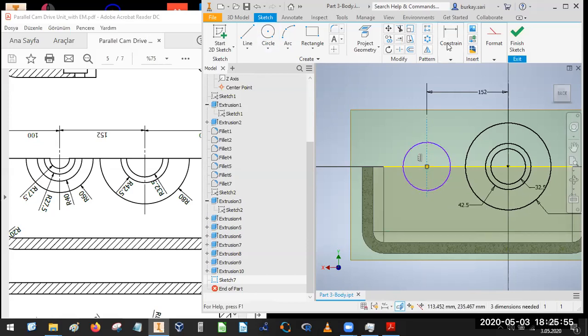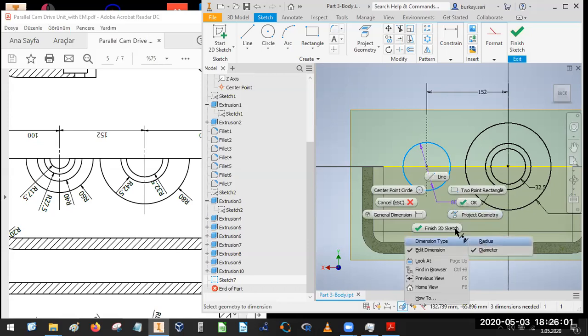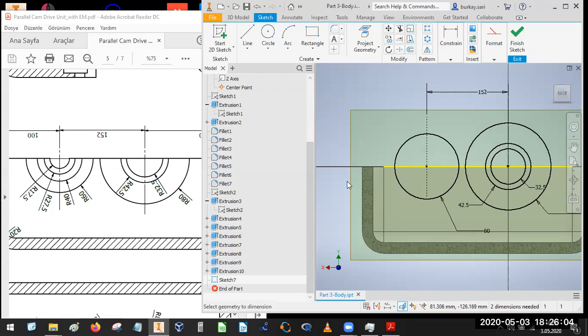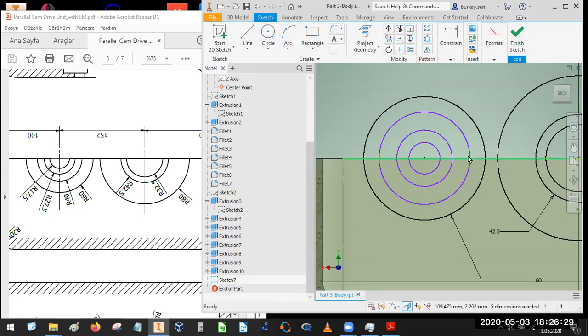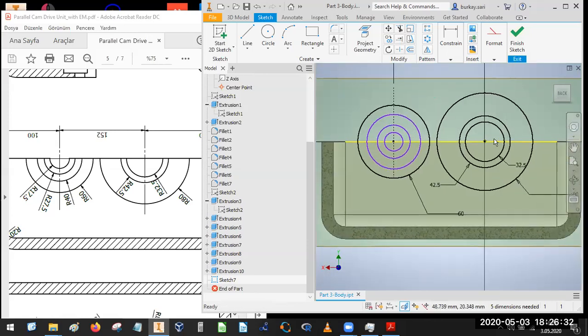As you see, when I give the dimension, I will just check my figure, which is the first one, the radius, it is 60. 60, 40, 27.5, and the last, which is 35 millimeter divided by 2, 17.5. I will draw 4 circles, at least 3 circles left here. 1 more. Okay. You can also make the cuts if you want, so you can make the trims because we have already a line.